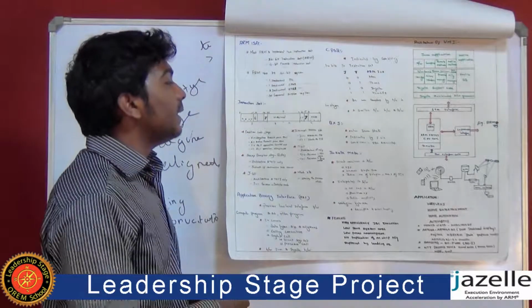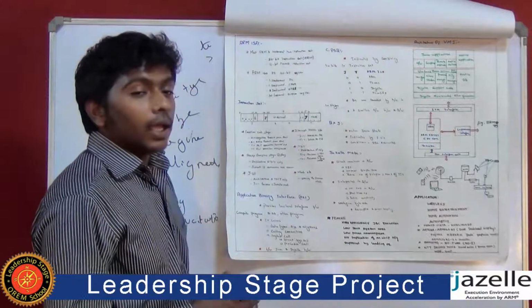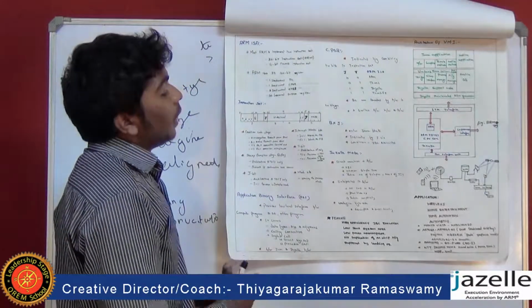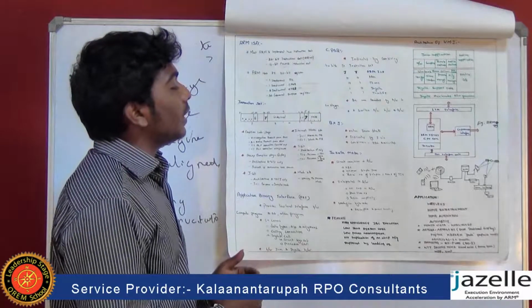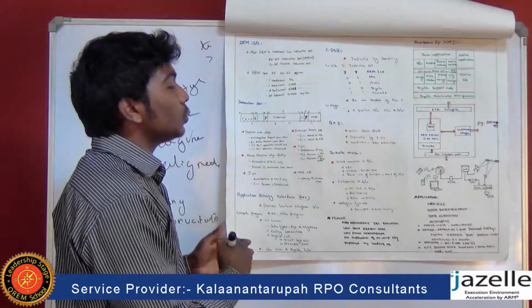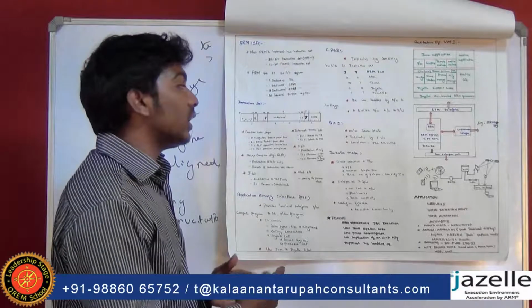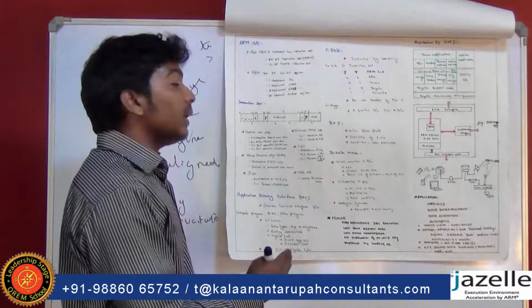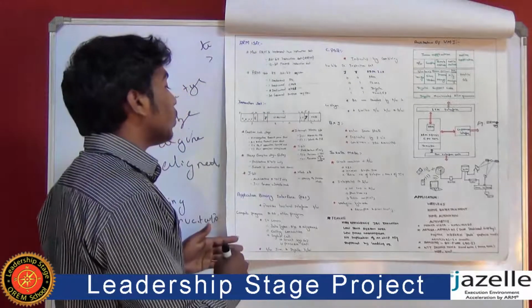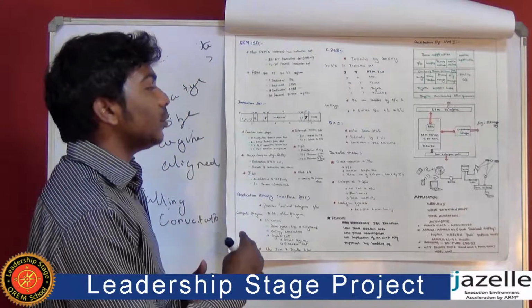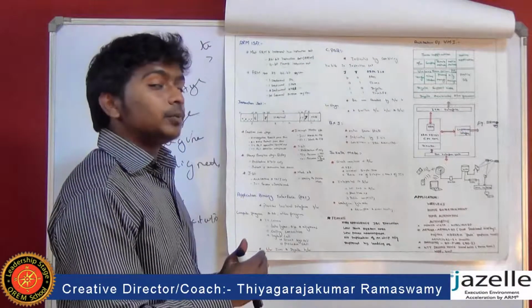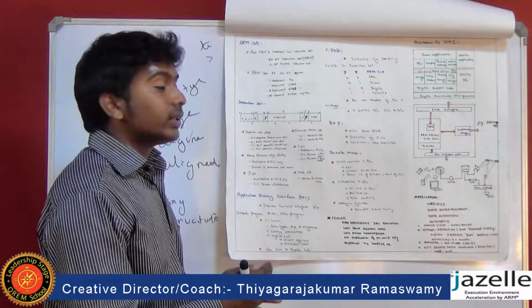The next one is BXJ, that is branch to Java. The name itself identifies that it is used to enter into the Java state, that is Jazelle state. It is identified by the J-bit. When the J-bit is set to 1, the Jazelle mode is entered. Based on some conditions, the Java bytecode is executed.